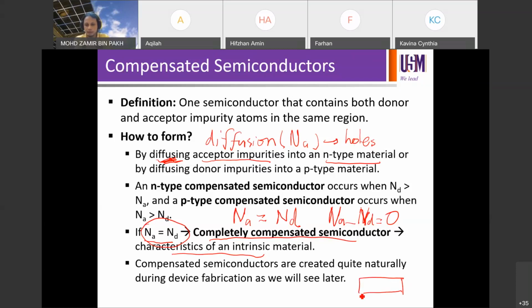So say if you run the project for your FYP with n-type silicon, then in order to form a p-n junction, you need to diffuse. So that's the word diffuse, by diffusion process, a very thin layer on top of your silicon with a p-type to make it p-type silicon, so that you're going to have a p-n junction eventually, p here and n, right? P sits on n. So to be able to do that, you need to go through this process.